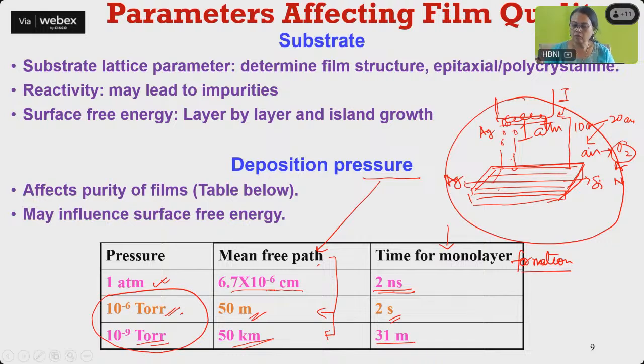Now, if I have a pressure of 1 atmosphere inside my chamber, this Ag atom, which has just come from my filament, will travel just this much distance before it encounters, say, an oxygen molecule or an argon molecule. So there is no chance of this evaporated Ag atom coming and sitting on my substrate.